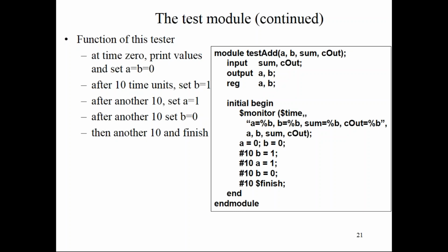For a particular time period, I have to terminate the module, so I'm using the $finish statement after a time period I have defined here. For example, after 600 nanoseconds I have to complete my simulation, so I use the statement 600 $finish. Then it will automatically terminate my simulation after 600 nanoseconds.